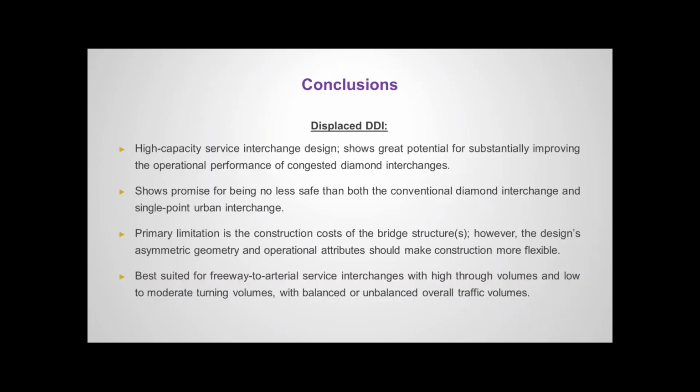And so, in conclusion, the displaced DDI shows a lot of potential for substantially improving the operational performance of congested diamond and service interchanges. The operational performance is probably the key benefit of using this design. It also shows promise for being no less safe and no more dangerous than both the CDI and the SPUI based on the preliminary conflict point analysis.